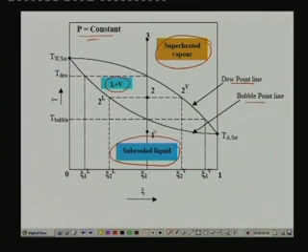As I explained to you, we started with a subcooled liquid. So, point 1 lies in the subcooled region. So, we started heating it, that means the temperature started increasing, and this is the point at which the first vapor bubble appeared. So, that is why this is the bubble point temperature at this concentration zeta 1 and at this pressure P.